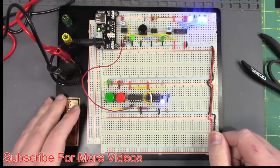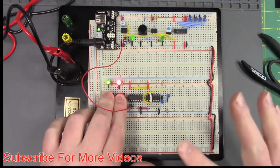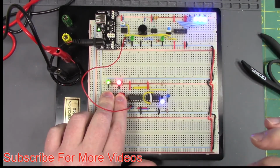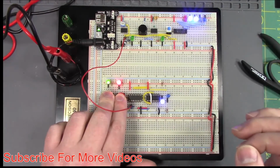But the interesting part about a JK flip-flop is if you hold down both inputs, it's supposed to flip. So it does it, and then it doesn't do that. And this is inherently why a JK flip-flop by itself is not the best option in a logic circuit.